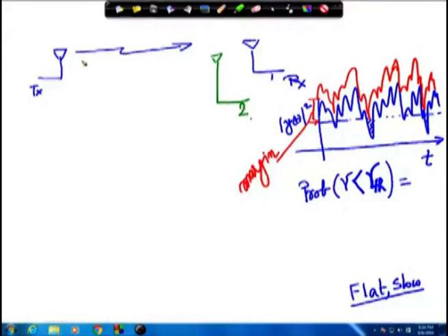And the same signal will now be received in antenna 2 as well. I have not sent any multiple signal, we have sent x of t, or according to our earlier description, s tilde of t in the baseband equivalent or the low pass equivalent signal. Whatever was received here, I would receive another copy of the signal, right. This is very clear, because there are reflectors around, and we would be getting scattered components.